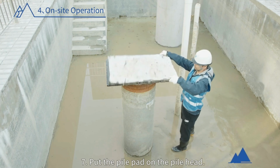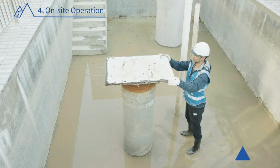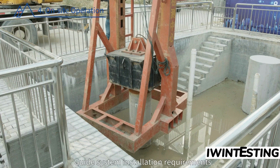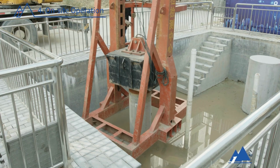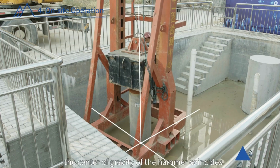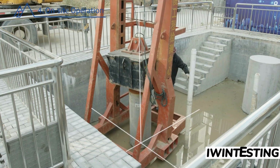7. Put the pile pad on the pile head. 8. Install heavy hammer and guide frame. Guide system installation requirements: the base is stable, and the center of gravity of the hammer coincides with the center axis of the pile.